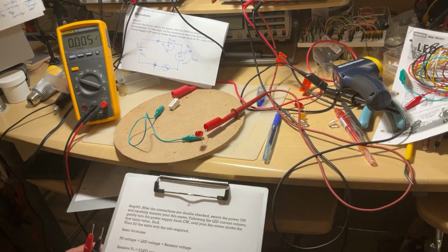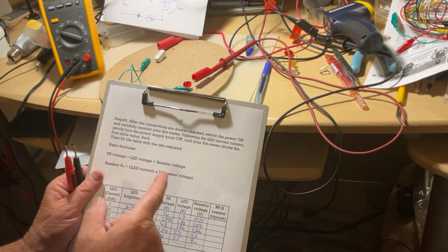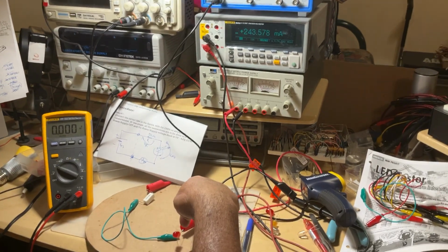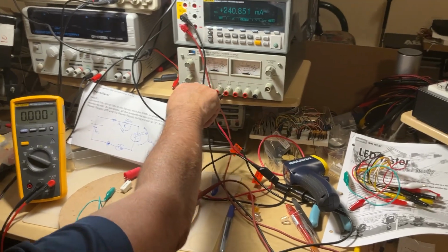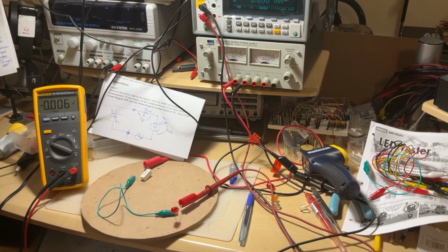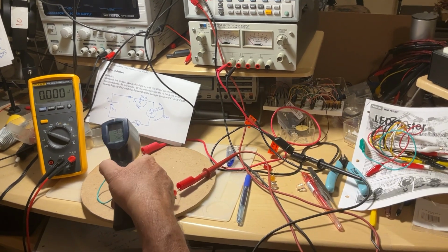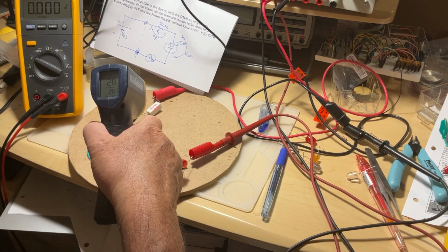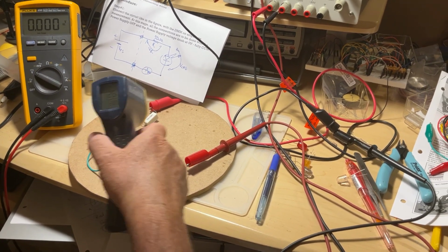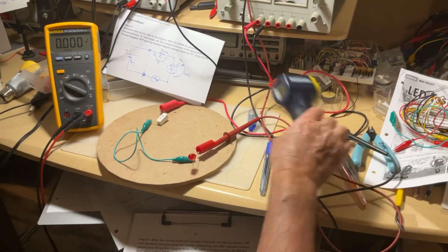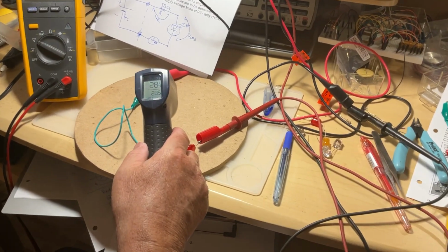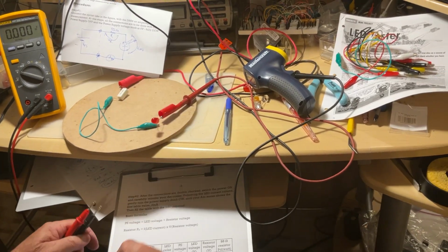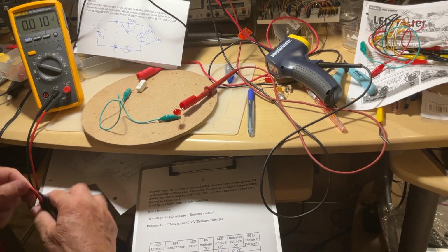So that's actually asking the question, what happens to the diode if you over-energize it? You see, the current is still passing through the diode. It's completely shorted right now, so it's not worth the effort to continue energizing it. If I take a measurement of the resistor, it's still not too hot because it's a 5-watt resistor. So the resistor is, if you take a look, 28 degrees, okay? But the diode gave up already. So this diode has to be disposed of after that because it's useless.